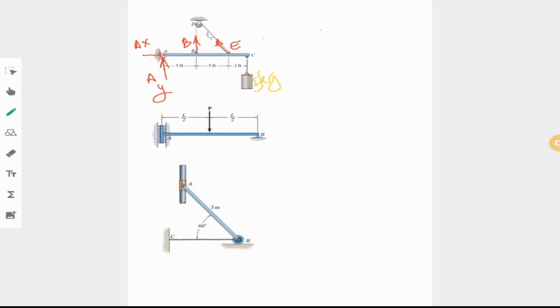But there is a good relation which we know about pulleys and cables. We know the forces applied on the cables which are going through a pulley are equal, meaning that if this one is B, this should be B as well. If it's not, this pulley starts to rotate, meaning that the moment of this one is not equal to the moment of the other. The moment of this one around this point would be B times R. R is the same for both.